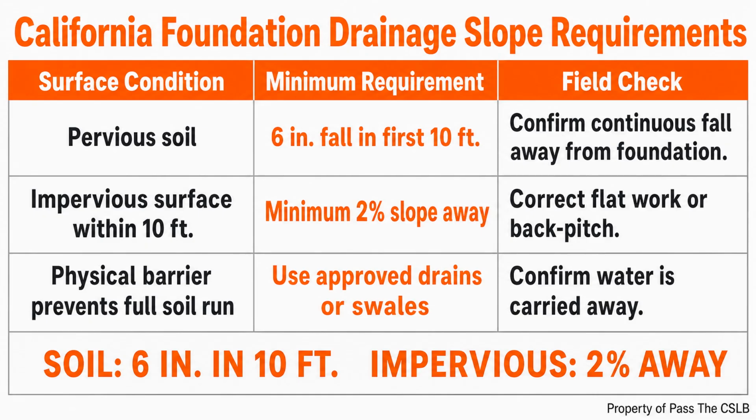First, identify what each mark controls. Is it elevation, working layout, utility location, or a legal boundary monument? Second, protect original control before equipment enters the area. Transfer information to working control only within the contractor's role. Third, never guess at a property line or reset a boundary monument. Bring in the licensed survey professional when legal control is uncertain or threatened.